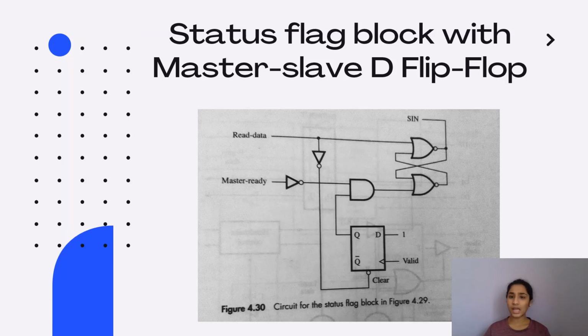Now, the state of this latch must not change while SN is being read by the processor, because during the transfer of information between Data N and the processor, Data N is still not ready to receive information. Therefore, SN should still be 1.